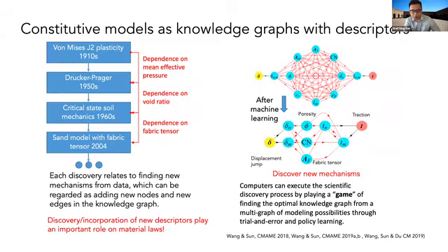If we look back into the development of plasticity or elasticity, we can consider that some of the progress of different constitutive models is related to introducing new descriptors. From J2 to Drucker-Prager, we introduced the mean pressure as a function to modify the yield function.